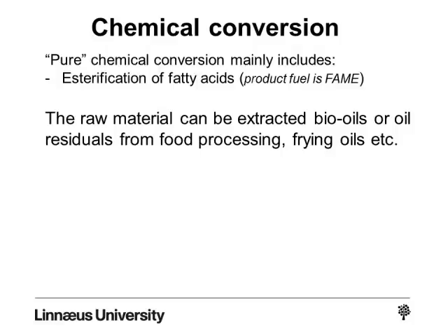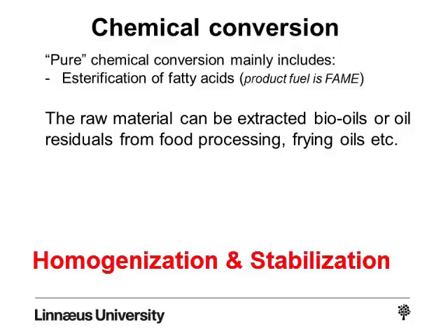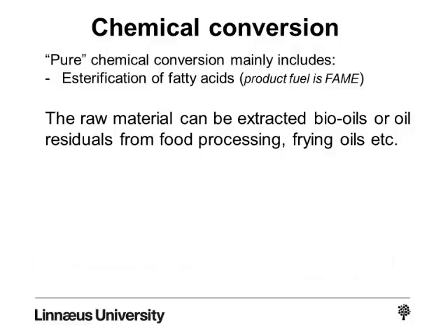And the idea with esterification is, one, to homogenize the material, and two, to make it more stable so that it can be stored. So these oils can be used directly, but using the esterification process, which basically means that the oil is treated together with alcohol to form an ester, means that its storage properties are improved radically.